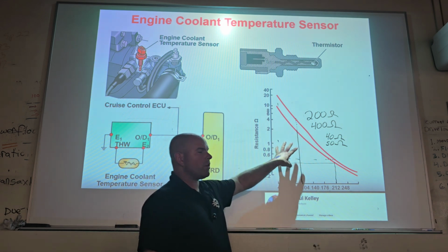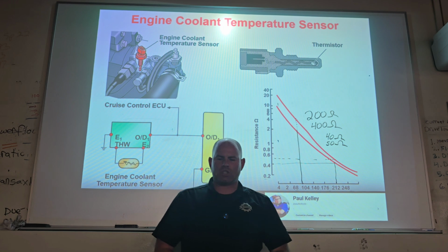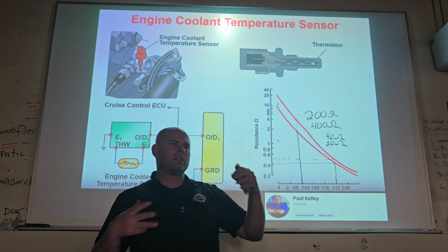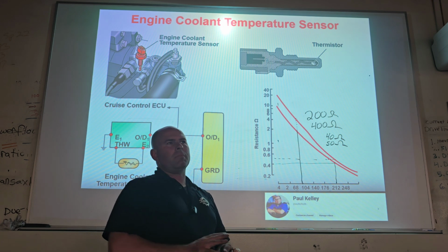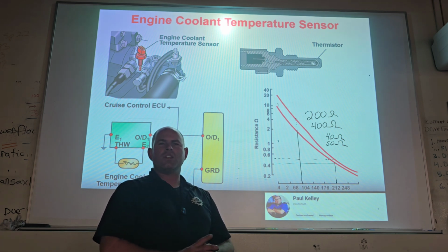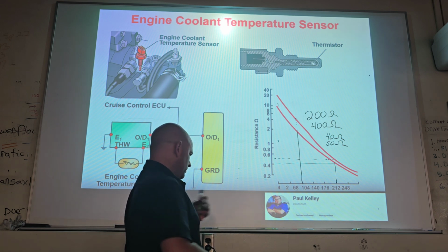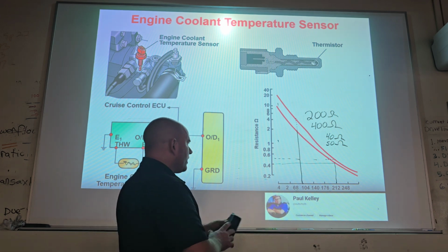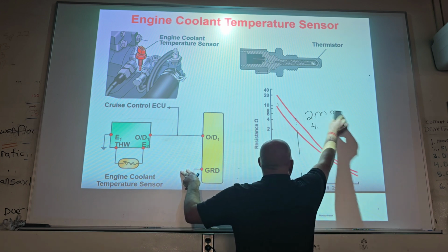So this is important when there's a problem, but don't jump to this and be like, oh, to check that sensor, I need to get TIS and I need to get all these specs. Just go about it in a much more practical way and check the live data at ambient temperature. Now, if it's off, then yeah, you may need to do more of this type of stuff. Cool? So that's how all those thermistors work.